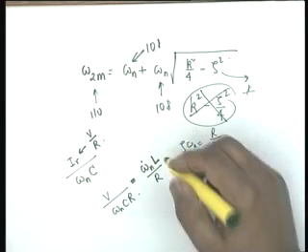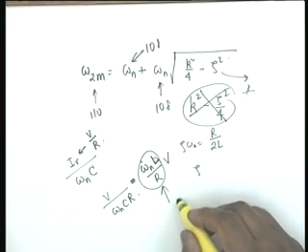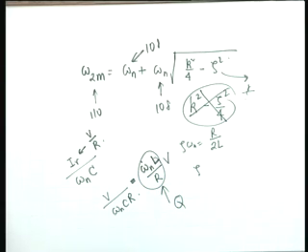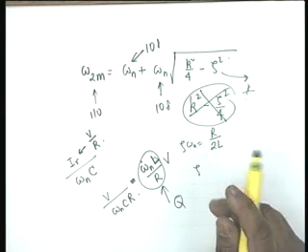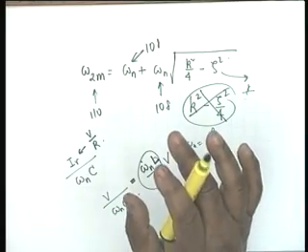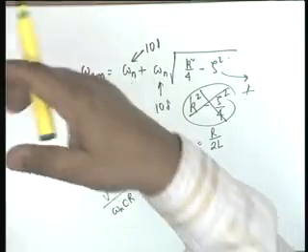Which is equal to omega n L by R multiplied by V, and you know this is the Q of the coil. So the voltage across the capacitor is Q times V. I am not complicating the situation. If you remember this, similarly you can show that the voltage across the inductor is also Q times V, where V is the maximum voltage of the applied source. V is either the peak value or the RMS value, it doesn't matter.